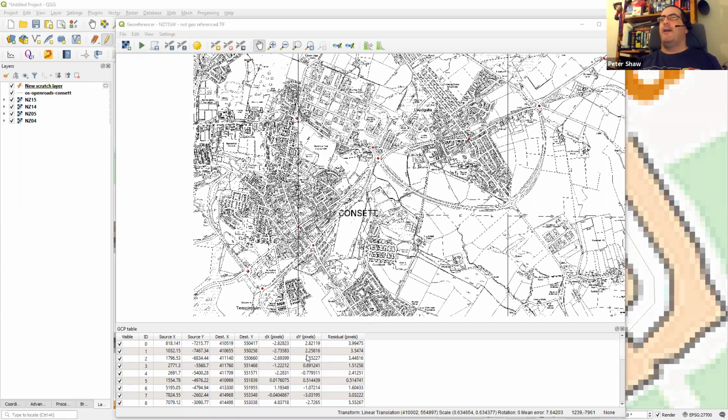And it's telling you these are the rounding errors that I've worked out. None of them are particularly drastic. However, if you georeference maps and you routinely see these sort of in the 50s, 60s, 100s, things like that, really big values, then you're not getting your georeferencing done very accurately. And you're quite possibly even using two different EPSG codes.